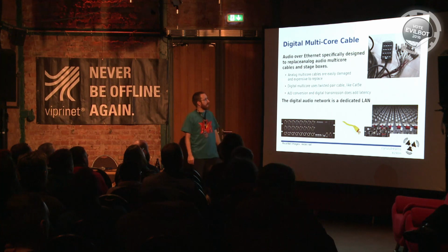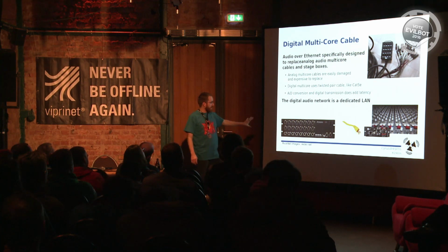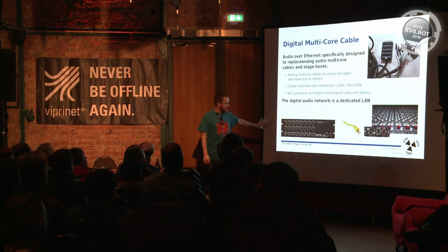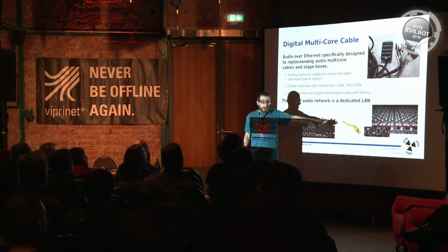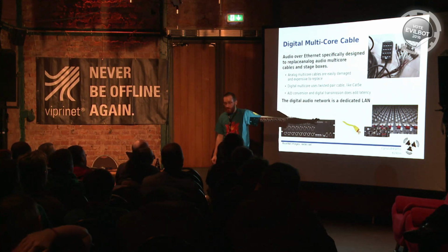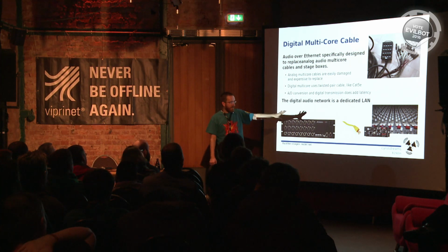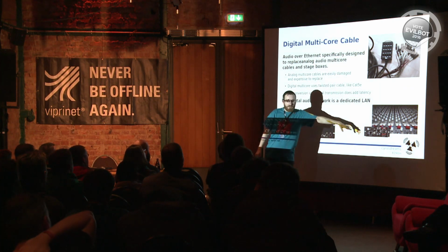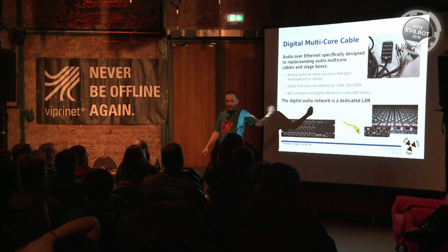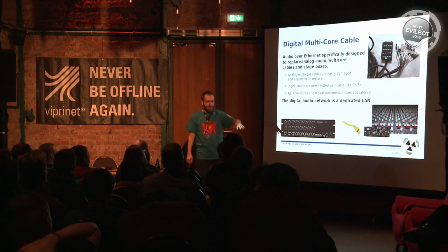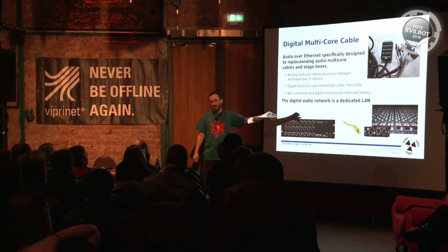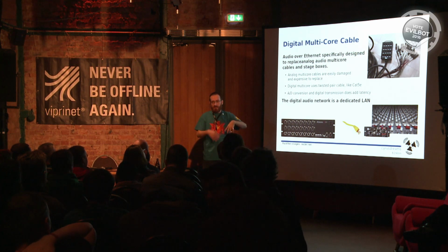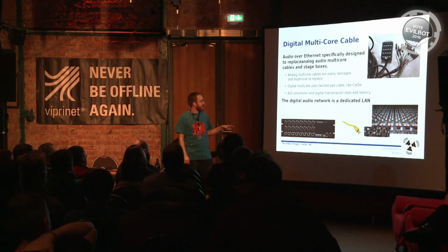Now audio over Ethernet is taking over this job. So you have on stage this analog to digital converter. In this case, that's a ROCnet. And you have a ROCnet Ethernet interface. It is separated from the normal LAN. You don't mix those. That's a dedicated LAN. And in your mixing console, you have an interface where the digital audio gets fed input into your digital mixing. Or you can have a converter that converts it back to analog audio and distributes it inside your mixing console.